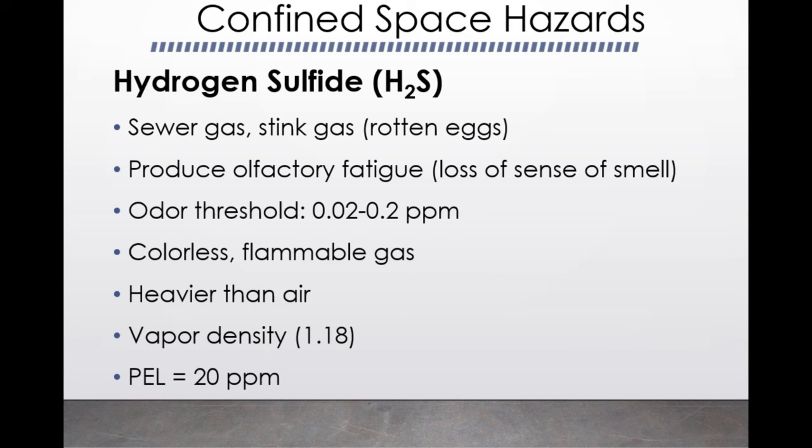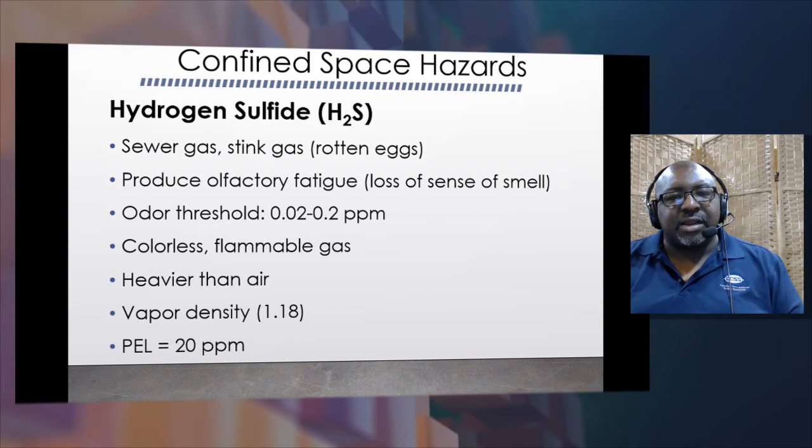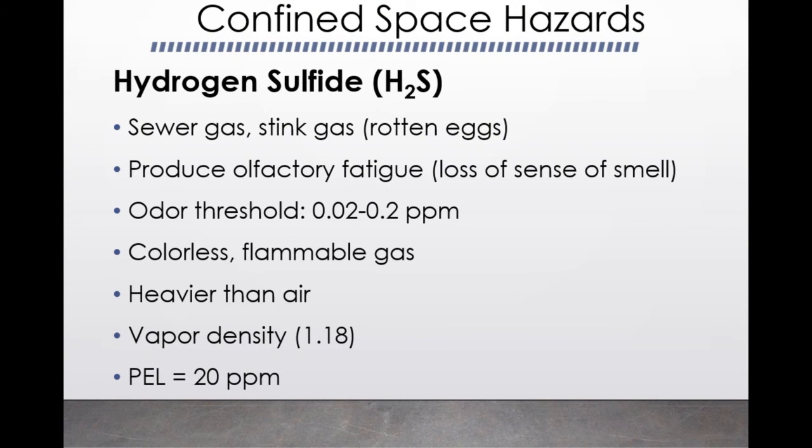Hydrogen sulfide is big, especially with any kind of sewer system. You're going to have that rotten egg smell, but don't get lulled into that because you will have a loss of olfactory senses. There is what's called olfactory fatigue, loss of smell, if there is too much exposure to hydrogen sulfide. And it is definitely heavier than air, so it'll be in the bottom of that enclosure. So you're going to need to make sure that you blow out some fresh air there. Your permissible exposure limit is 20 parts per million.